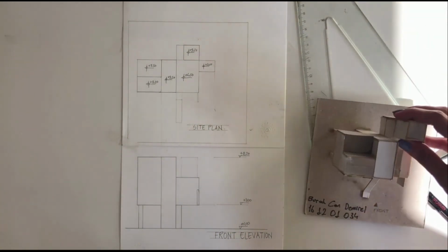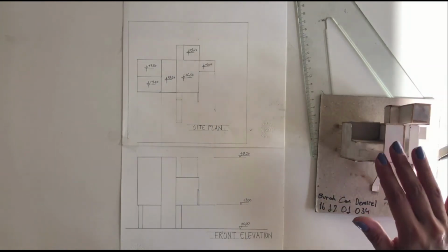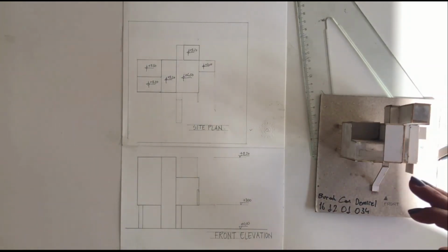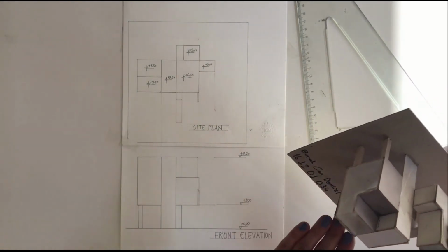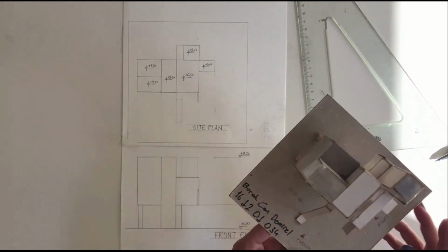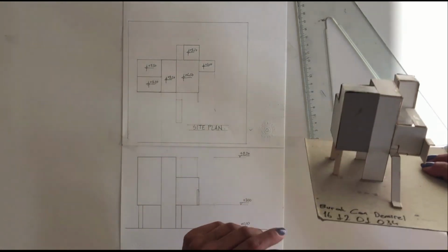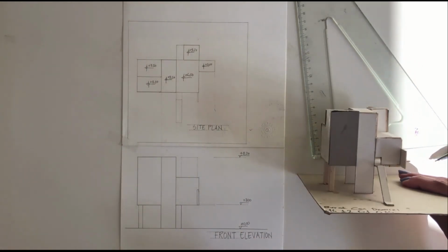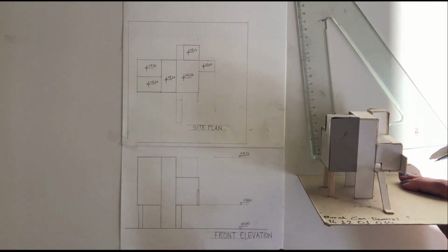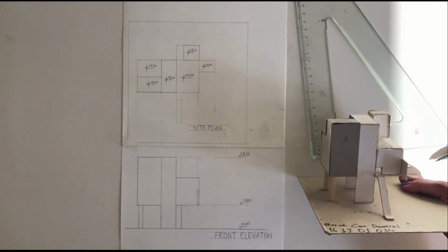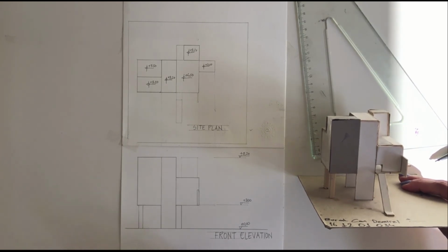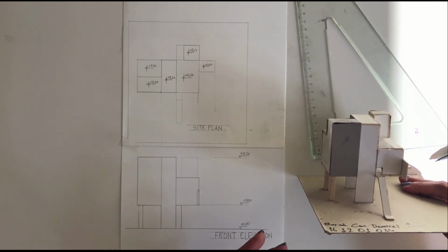Again, a site plan or roof plan means that we are looking at a building from the top, from bird view, and we are drawing all the surfaces we see. And an elevation is more or less the same. We are looking at a building again at 90 degrees, and we are making orthographic projections. Again, on elevations, we draw all the surfaces we see.